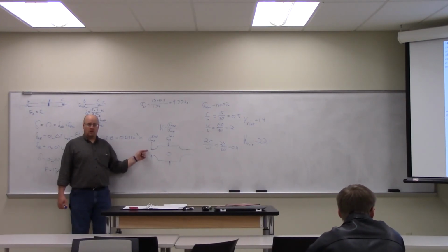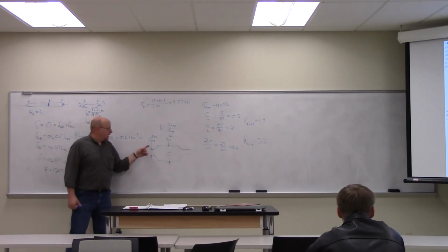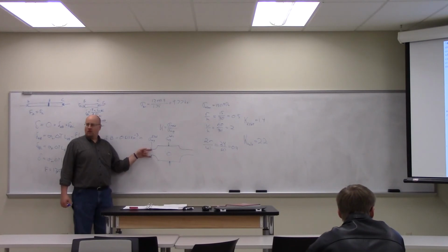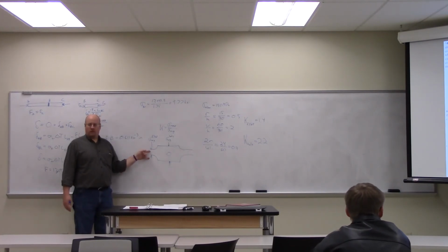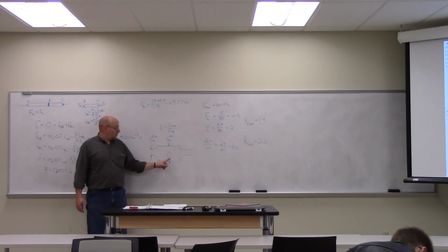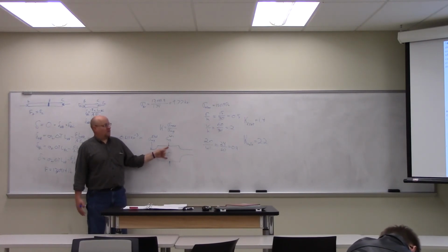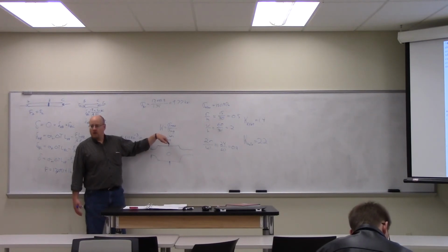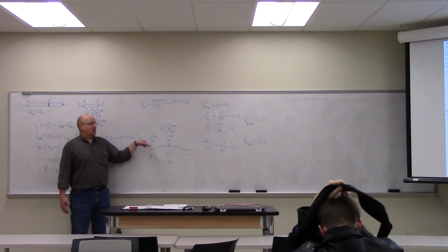Does that make sense? We don't have time to do it now because we're out of time, but we have to go back and calculate the average stress in the fillet, P divided by cross-sectional area. And the average stress here, P divided by this cross-sectional area, now reduced by the hole. So the cross-sectional area here is going to be 36 times 20, the depth. And here, it's going to be 30 times 20.